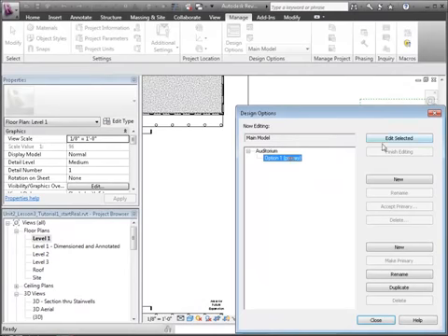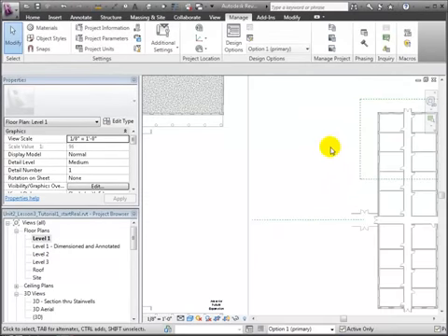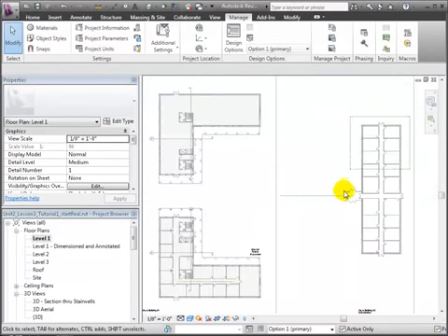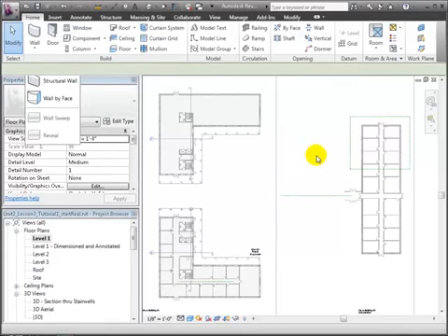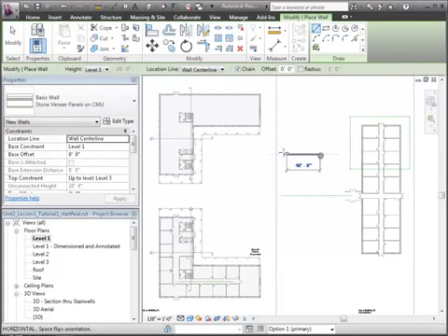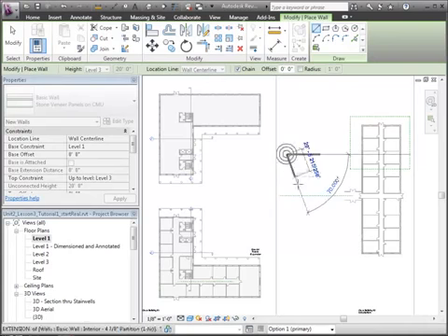Click on the option and click Edit. This takes us to option 1, which currently is empty. Everything else in the model is grayed out since it is not considered part of the option, but rather the main model. As we model option 1, we certainly want to still see the main model for context and to understand how our option interrelates with it.